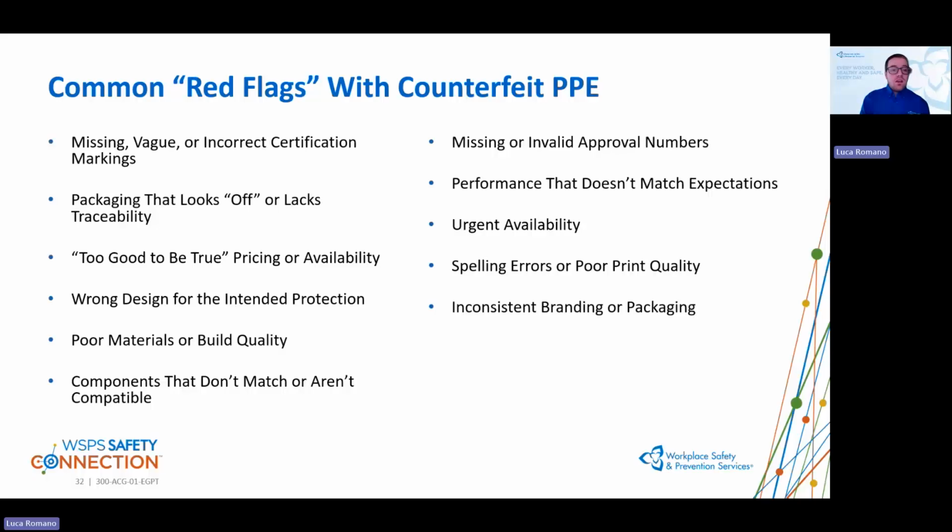The packaging might look off or it might lack traceability. So let's say you're used to a certain brand that you buy from. If you're noticing that something's off with the packaging itself, or you can't actually trace back where the package came from in terms of the supplier or even the manufacturer, those are important red flags. Sometimes too, you could have too good to be true pricing or availability. So these limited time deals, you have 500,000 units that are suddenly available for 1 cent each. If it's too good to be true, chances are that they are.